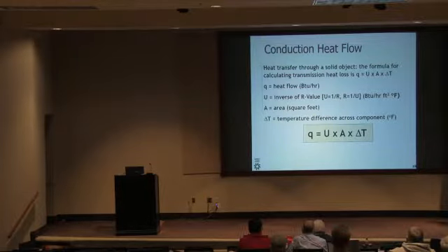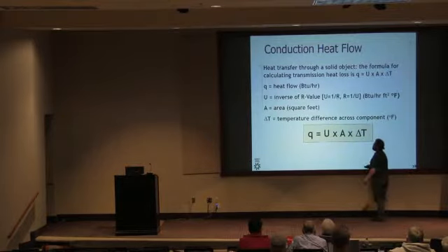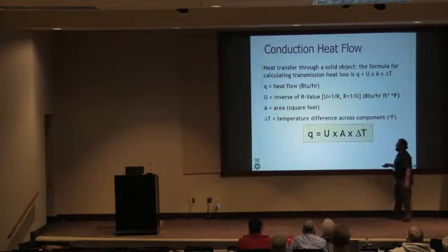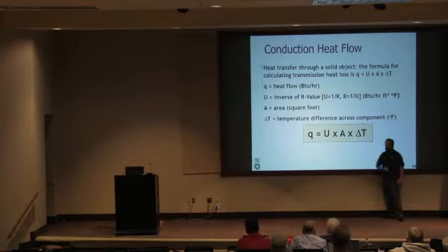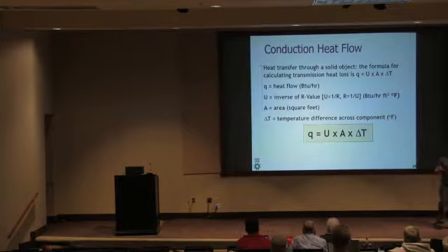Because the insulated ceiling has a better U, it has less area. On the other hand, it has a greater delta T. That roof deck has a lower delta T, but it has a worse U and it has a greater area. So on paper, people can look at a spray foam roof design and say, oh, it's going to have more conduction. It's going to be a worse performing assembly than if we insulated the ceiling.